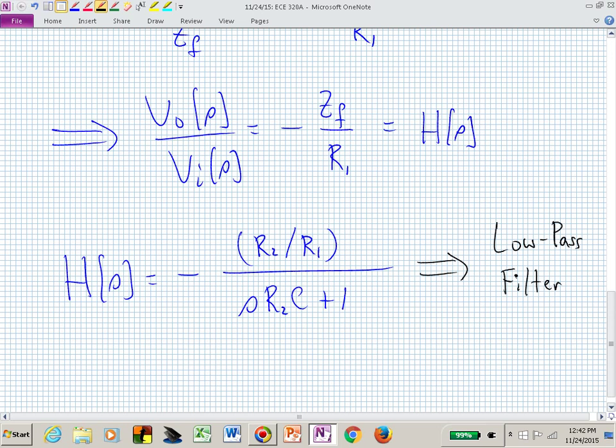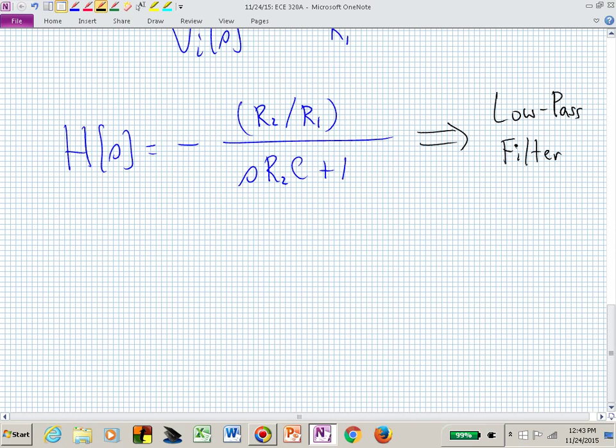If you looked at the very low frequency, let's say DC, S is equal to 0, that's the smallest that denominator term is ever going to be, which is 1. If you start increasing S, and really we're going to be replacing S with j omega, you're increasing j omega, now that magnitude of that term is getting bigger, so you're just continuing to get smaller as the frequency grows. And what does the frequency response of that low-pass filter look like? Just in an approximation sense.